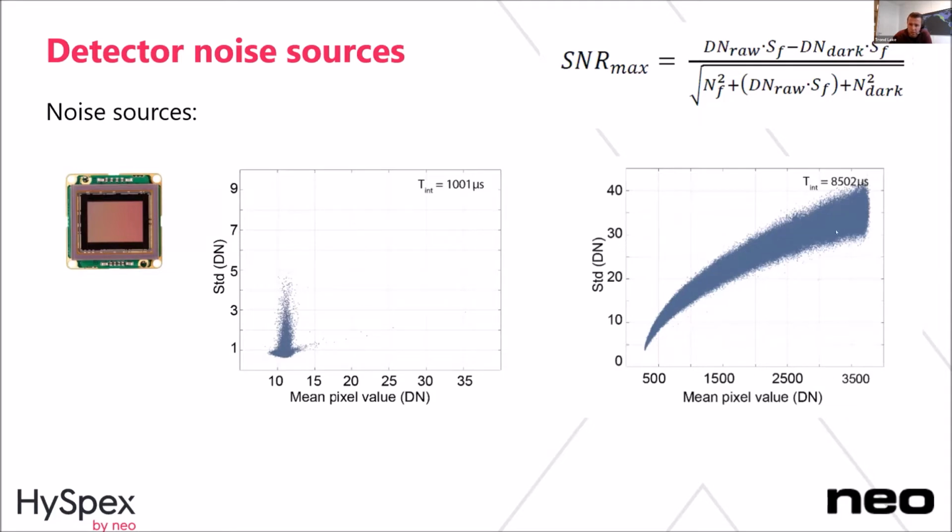Then you have this very nice curve here. It's also the background in my LinkedIn profile, because this is how a detector should be. It should always be photon noise limited. And this is the photon noise curve. It's Poisson distributed, and that's the physical limitation of, or should be the physical limitation of any detector, right? Yeah, so basically when you're going up towards saturation here, you will have a noise which is the square root of the number of photoelectrons generated at that digital value.